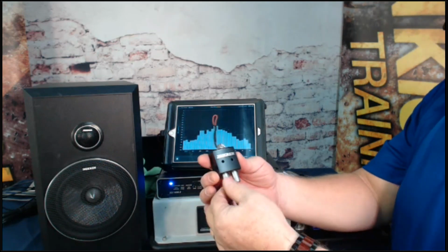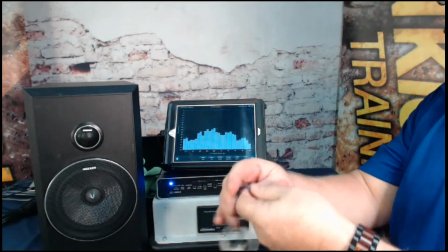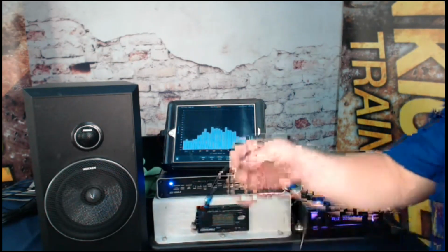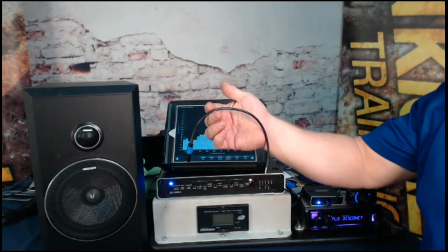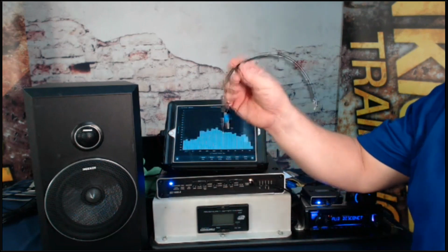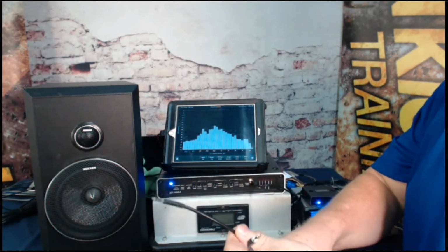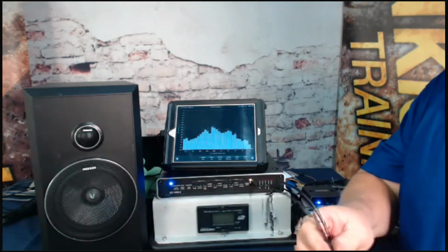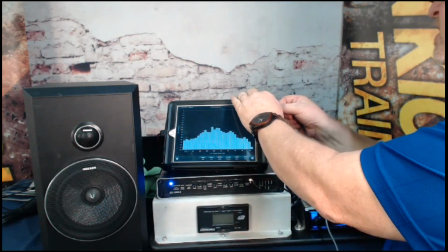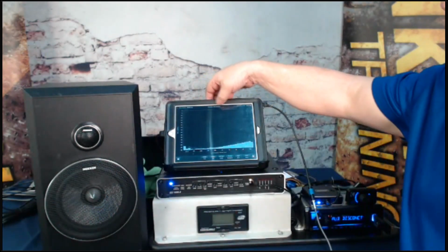From there, we're going to go from an RCA to a 3.5 jack at the end of this long cable. Now is the magic tool. This is very similar to the KISLOC. This is a mic to line adapter. It takes the signal from line level down to mic level, and it gives me the sleeve for the microphone input. With any free or paid RTA app that you have on a tablet, a phone, or a laptop, we can plug this into the microphone input, and you're going to see on this particular unit, it switched to headset microphone.